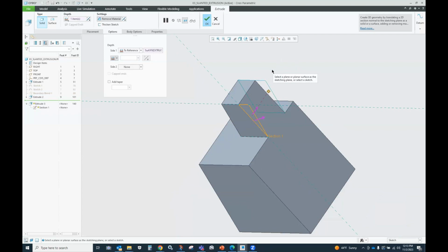Okay, or through until might be another option for that because maybe I got to go through two protrusions. Maybe there's a third protrusion that I don't want to go through, so that'd be through until, right? I'm telling it where to stop. So that would work as well. All right, so these choices are pretty important because they are references and they're going to determine how robust your model is. Okay, now what's the other thing I could have done better in this case?